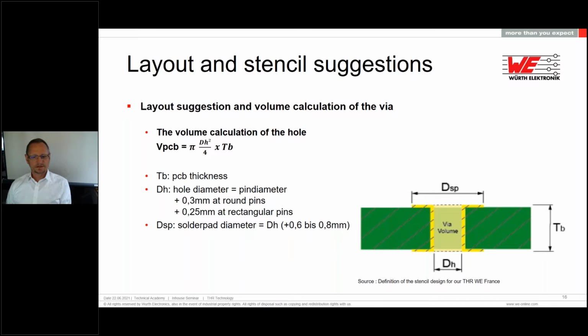So, easily explained, we need sufficient solder paste for an accurate solder joint. And we have to keep in mind that approximately 50% of the volume of the solder paste, in unsoldered condition of course, will be totally gone after the soldering. These are additives and fluxes that evaporate in the process.